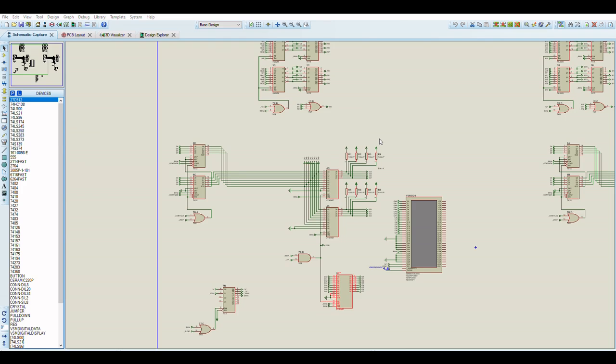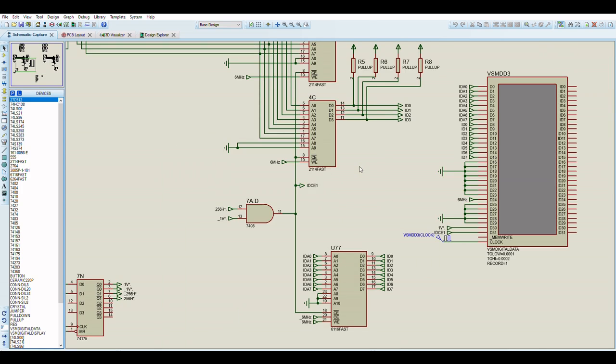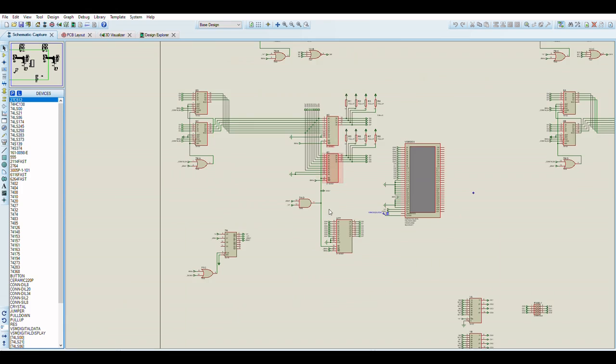I wanted to have consistent RAMs, so you can see here on the schematic, this is actually enabled in the simulation and enabled on the PCB layout. The original 2114 RAMs, which are 4-bit RAMs, are excluded from the simulation. These 4-bit RAMs are really excellent, they're really nice and fast, but I just wanted to use these RAMs instead. I didn't want to have two chips, I just wanted one chip. So that's what I did. But I've kept it in the schematic just in case.